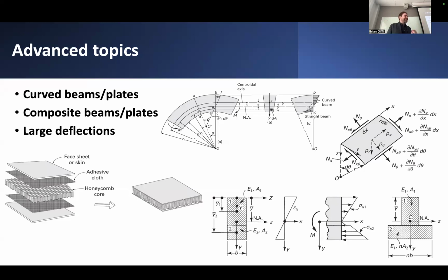To really analyze that situation, what you'll find is that, as I alluded to in the previous lecture, it's no longer appropriate to assume that the stress variation through the full depth of this composite section, which has a concrete deck and steel I-girders underneath it, is linear. It's no longer appropriate to assume a linear variation of stress through the whole thing.